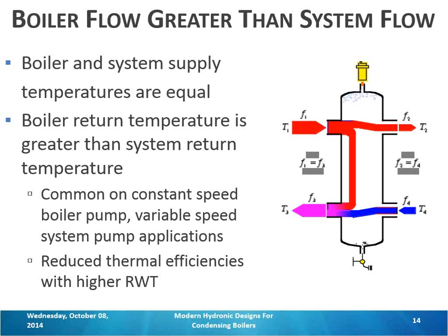Right. Or at the very least, it's raising the temperature and you have less condensate, right? Yeah. It's lowering your efficiency. You have to burn more fuel to get the same output to your system. And this can be avoided by using variable speed pumps on the boilers itself. But that adds cost, it adds complexity. There's a finger pointing of who's going to control it.